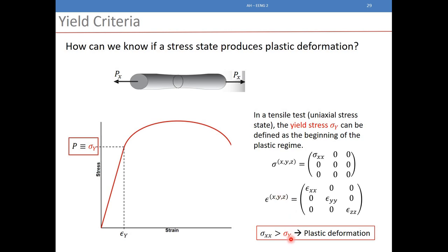This is sigma y, just a symbol to symbolize the word yield, because this is a property of the material. It is a constant for any material, while sigma x here is the force over the area, depending on the force that I am applying on the load. So for the simple tensile test, it's very simple. If the stress that I have is greater than the yield strength, I have deformation; if it's less, the design is safe. So there's nothing complicated here.